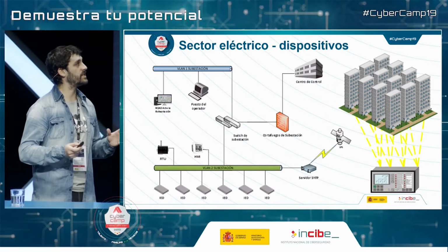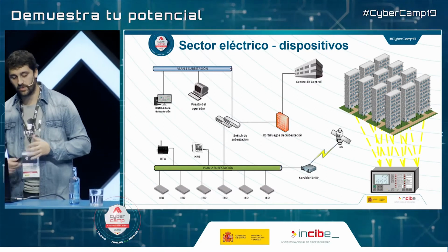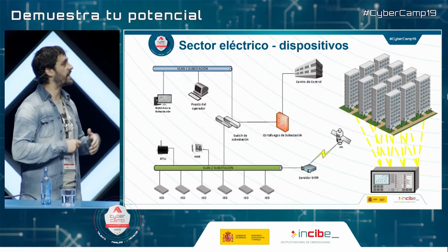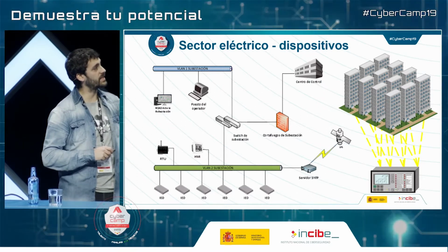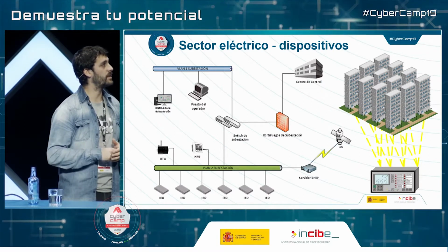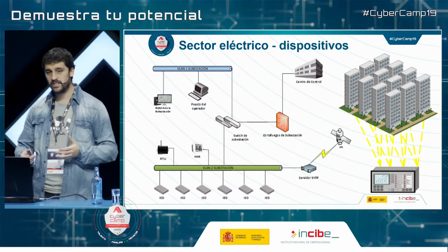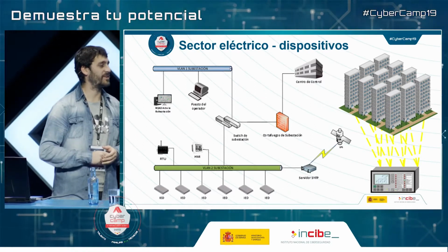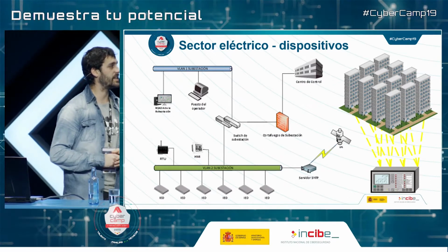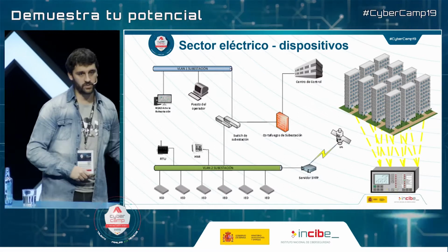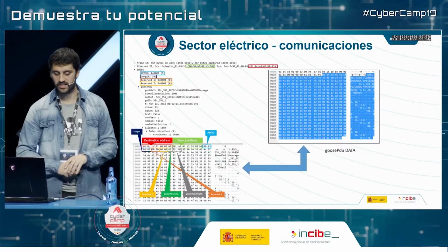There are devices at the network level, such as switches and VLANs to segment the network. You can also have a small SCADA, a local SCADA, in order to see how the process interacts. And in the stage of visualization, you also have them in the control unit with a firewall, if there is one, or with some network devices. And then we also have the SNTP server, because in the industrial sector, timing is quite important.